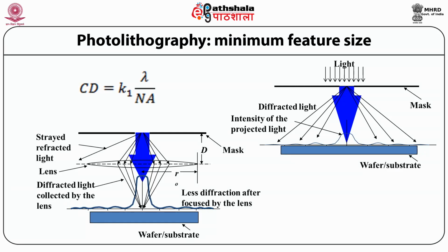Photolithography. In the case of photolithography, light is focused through a lens onto a surface to write pre-designed patterns. A thin polymer film is spread over a surface of the sample on which the artificial nanostructure has to be created, and wherever the light hits, the polymer hardens.